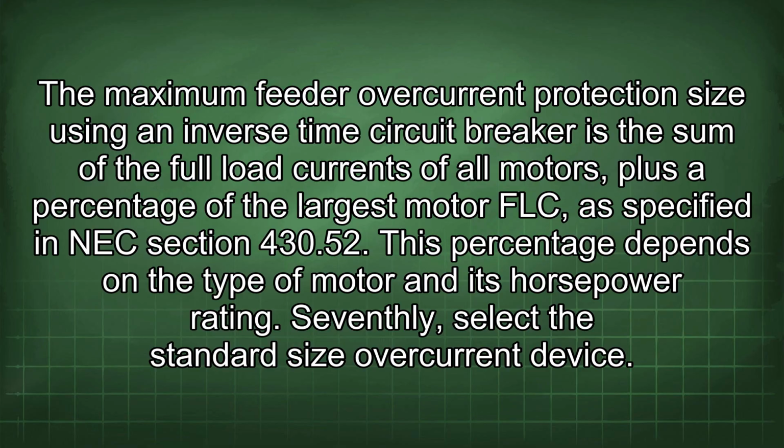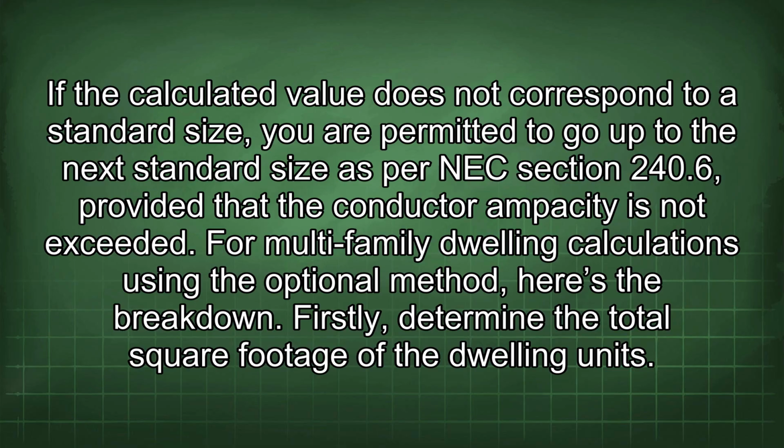Seventhly, select the standard size overcurrent device. If the calculated value does not correspond to a standard size, you are permitted to go up to the next standard size as per NEC section 240.6, provided that the conductor ampacity is not exceeded.